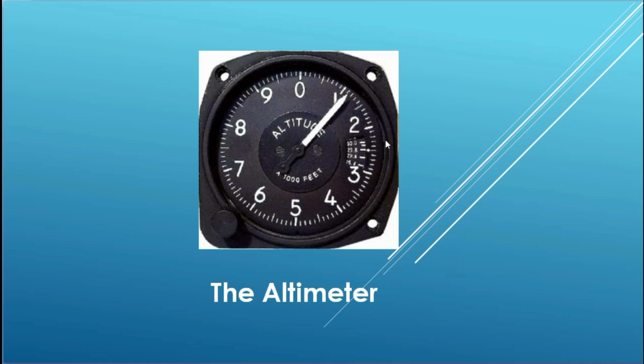The way we do that is we contact an organization like ATIS, or an online organization, that will give us an accurate barometric pressure for our local area. Then we just dial that barometric pressure in with the knob here on the lower left of the altimeter. And you can see the barometric pressure in this little window, which is referred to as a Kollsman window. We're going to use a microcontroller and some components to make a digital version of the altimeter, complete with barometric pressure setting.